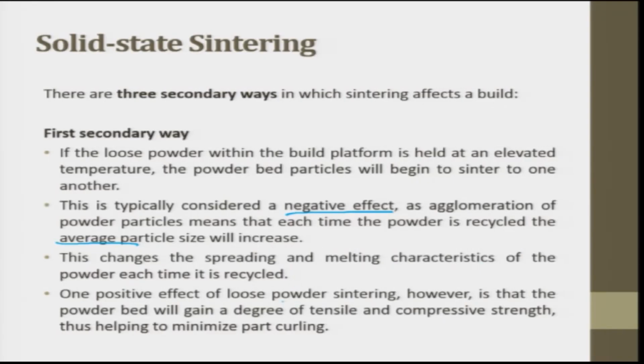One positive effect of loose powder sintering, however, is that the powder bed will gain a degree of tensile and compressive strength, thus helping to minimize part curling. Okay. So when there is pre-sintering happening, you will also have an advantage: curling will not be there.